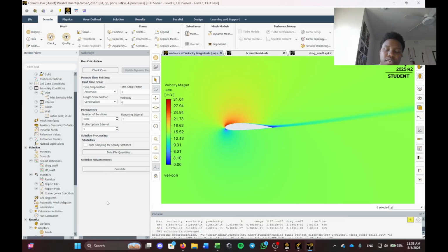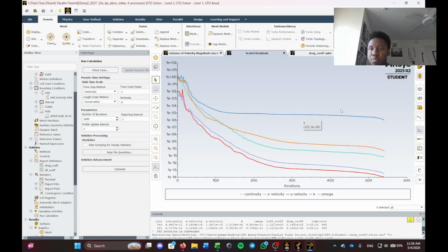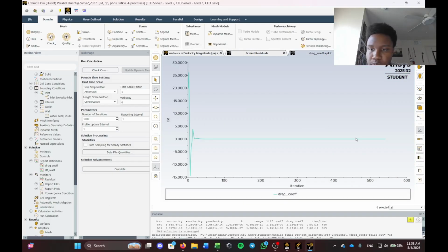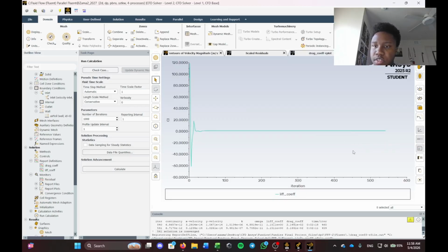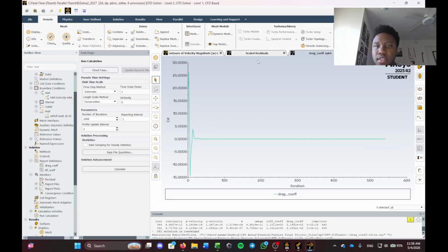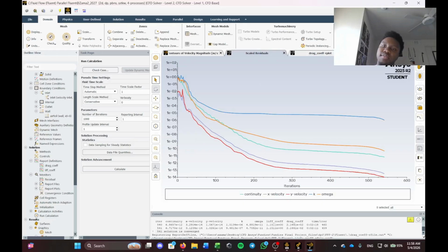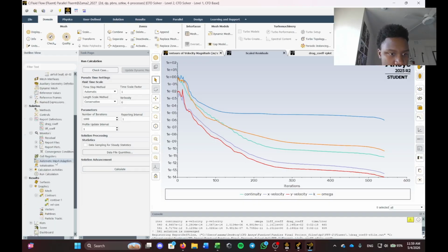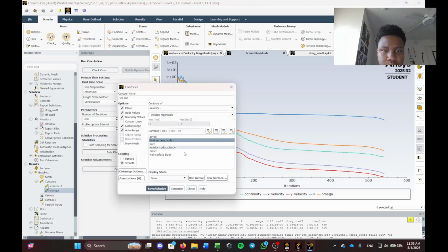541 solutions converged. This is why it's good to set it to 1,000 instead of limiting it to 200 or 300, because giving it more space to become more and more accurate is what we want. You see, we can actually see our drag coefficient there. It would make sense that our lift and drag are higher versus angle of attack, but you are going to get to a point where that kind of begins to decrease. But anyway, let's go down here to our contours here.